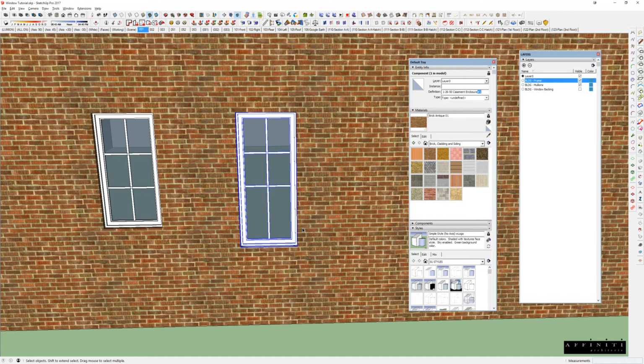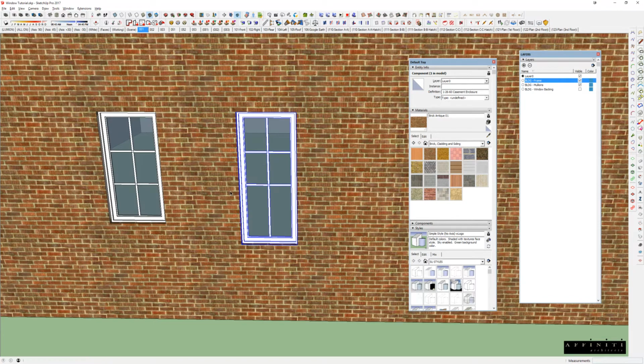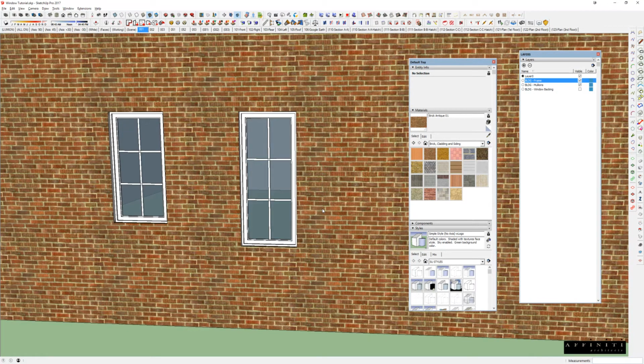Now that could be good or it could be bad, because maybe I want to keep this one as a 5.0, and so I can just come in here and rename this to be 12660, and I'm done. And I can, like I said, adjust my mullions really quick. So again, it's not right or wrong. It's just knowing the implications of what you do that will change.